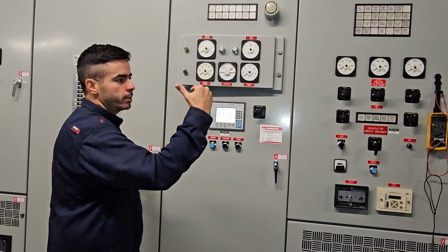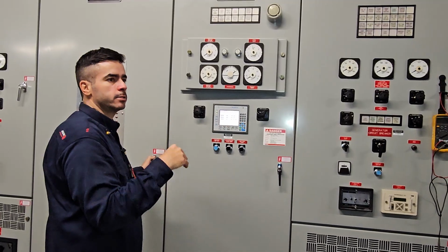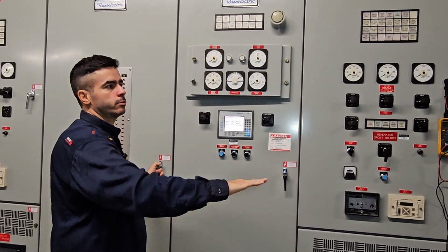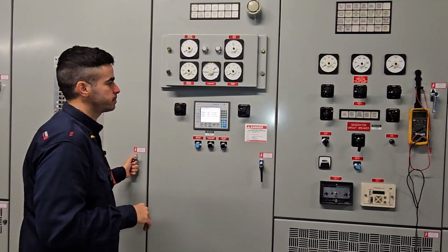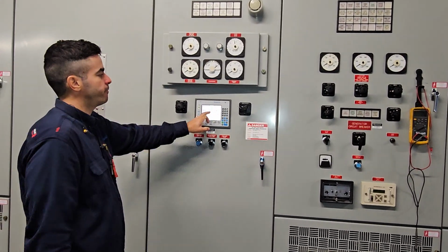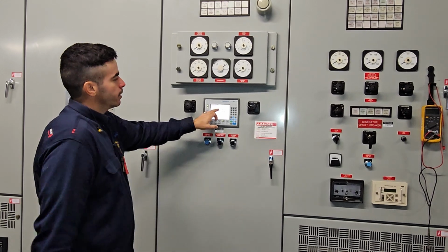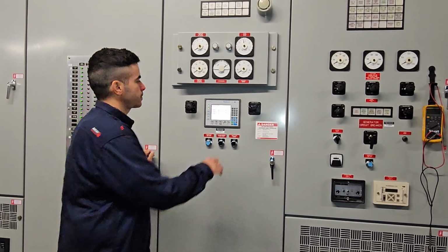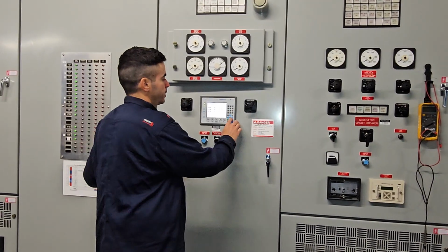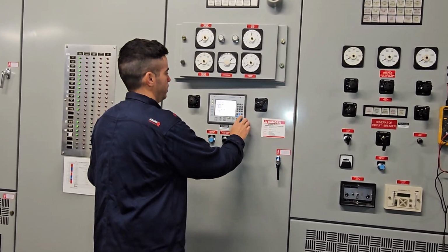So they will have a mode where the generators will automatically disconnect from the bus and go to cool down and eventually go to standby condition. So they're not running all the time during an outage. That's why we select a sequence. The higher number is the first one that is gonna kick off of the bus. But at first, everything comes on. The system doesn't know what's going on, so it just calls for everything.